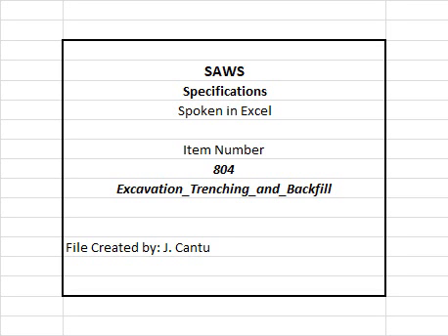5. Quality control testing. The contractor shall be responsible for compaction in accordance with the appropriate specification. A. Compaction tests will be done at location points randomly selected or as indicated by the SAWS inspector/test administrator, per each 18, first lift from bottom, and 12-inch loose lift per 100 linear feet, at a probe depth of 6 inches. 1 per lift per 100 feet. B. The inspector shall determine the depth at which the density test shall be taken. C. All depths shall be considered for testing without a predetermined maximum or minimum.